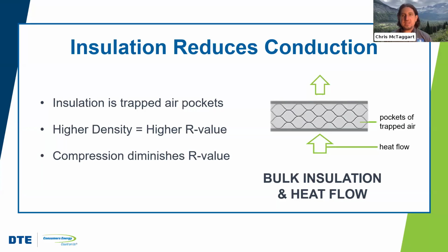You might say, well, that doesn't make sense because what about foam board insulation? That's very dense. Doesn't that mean that basically the foam is just pushing through? No, but the foam has very tiny little microscopic air pockets. And that's why foam tends to have a higher R value than other insulation products.